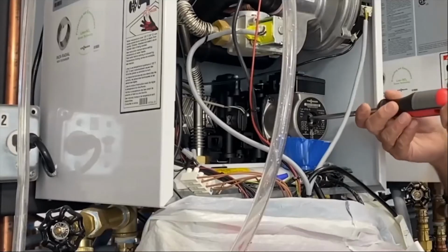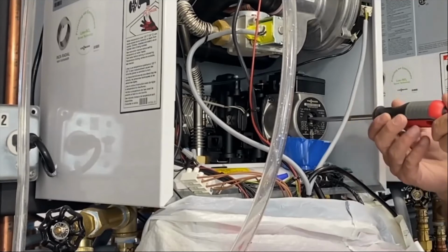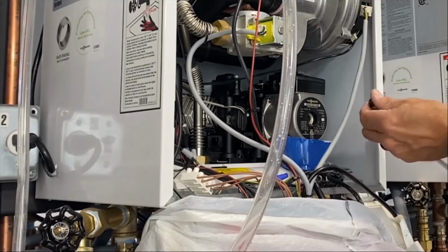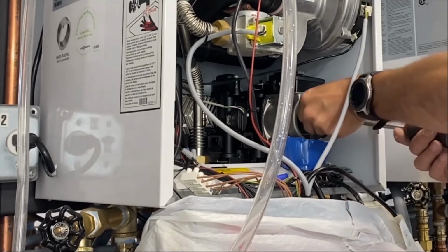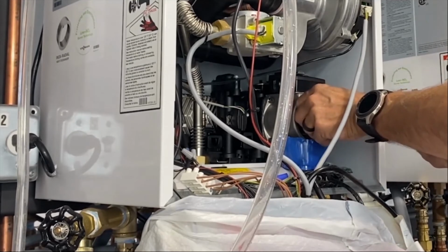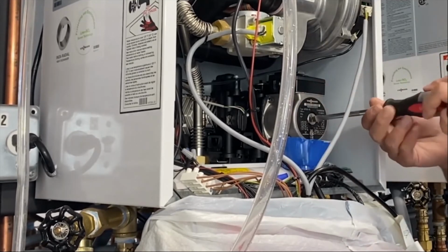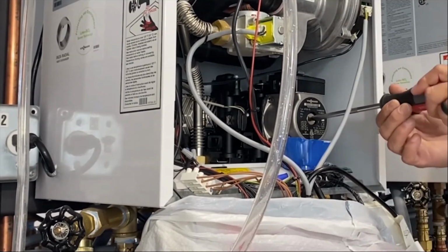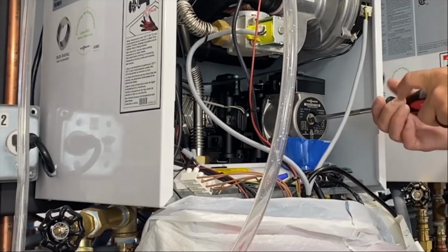And you're going to turn it to make sure that your shaft is free of any debris, or the shaft is just not frozen. And as you can see, that small little cup is catching all the little water, but if you don't have a cup, a rag is fine, because you don't get a lot of water out of this boiler while you're doing this. And I do have all my valves open now to make sure that we're getting water into the system and bleeding it at the same time.